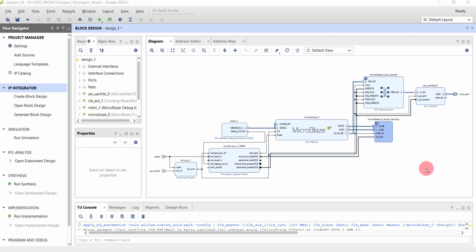Now we'll start considering the debugging techniques that we have when we consider the embedded system design with a MicroBlaze, right? The first debugging technique, which is a hardware debugging technique that we'll consider, is the usage of an Integrated Logic Analyzer, right? So in this specific video, we'll be understanding the entire process of how you probe an ILA to understand the transactions that are happening on a net, and then how you run the entire process to see the signal transitions